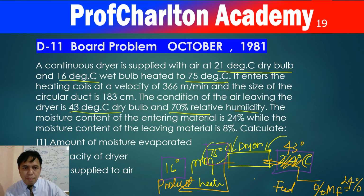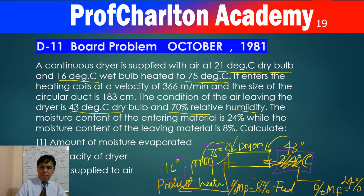24%. While the moisture content of the leaving air, expectedly, should be less than that of 24 because it's already dried somehow. Now, some portion were dried, some of the water were evaporated. So here, the percent moisture of the product, percent MP, is how much? 8%. Okay.